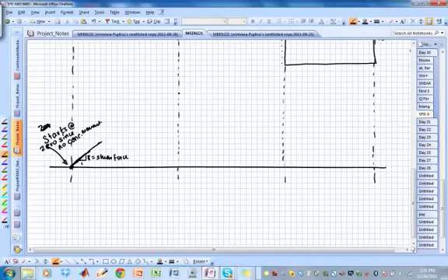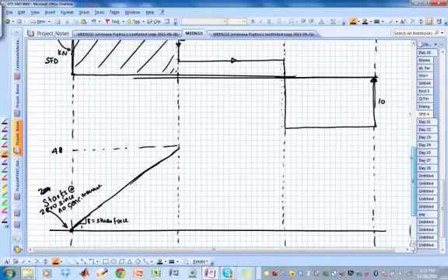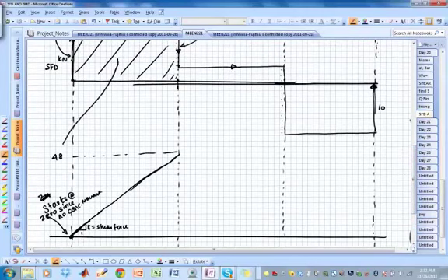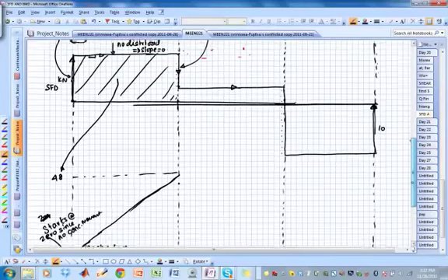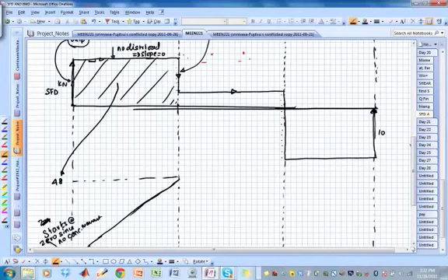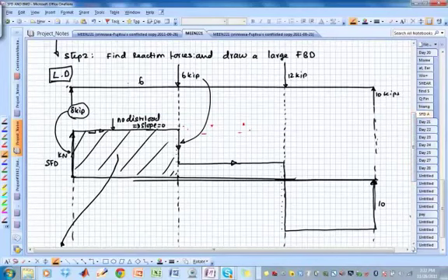So it goes like that. And so that's 48, and just to make sure, that's the area under the curve. Why is it a straight line? Well, for two reasons, right? I can look at this and I can say slope is constant, so it's a straight line. I can also look at here and I can say curvature is 0 because there is no distributed load, so curvature 0, so straight line.